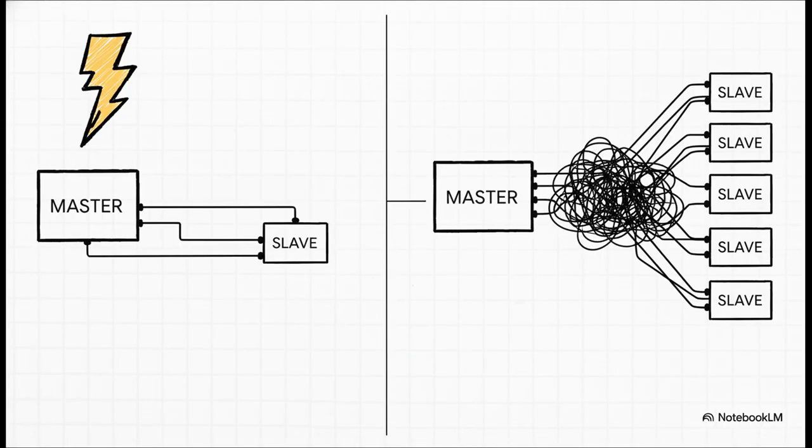It's all a trade-off. SPI is incredibly fast, way, way faster than USART. You see it all the time in things like high-speed memory chips or SD card readers, where you just have to move a ton of data and fast. But the downside? Wires, lots of wires. You need one for the clock, a couple for data, and then you need a dedicated slave select wire for every single slave device you add. It can get pretty crowded pretty quickly.